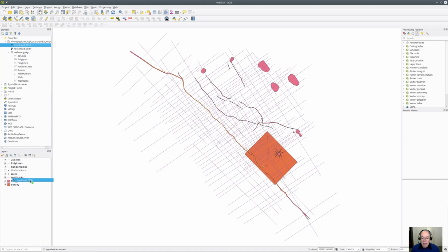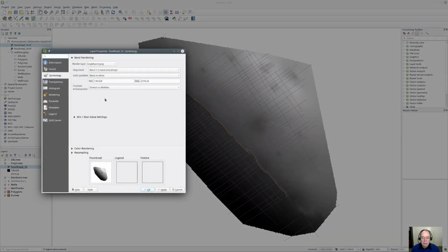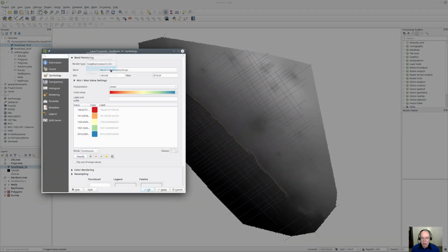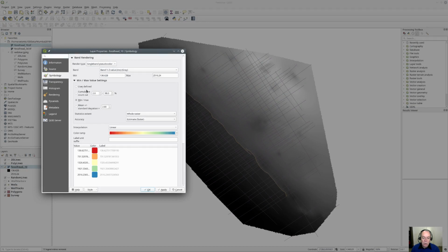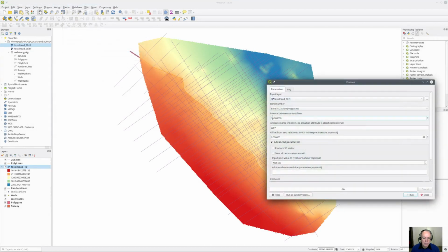You can also drag in the Geotiff files. Now, the regional time horizon has only a single layer and is best displayed using pseudo-color. We can also use some of the raster tools within QGIS to do things like generate contours. QGIS print layouts